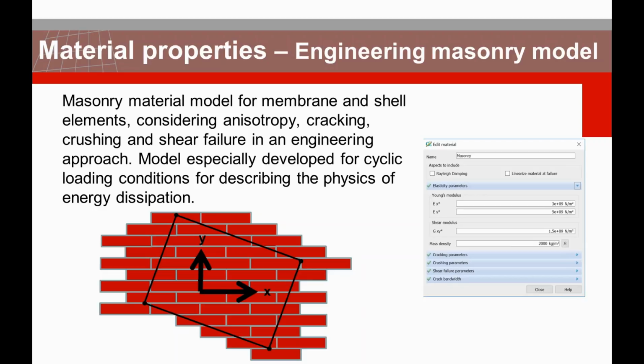So when there is a crack, the model is anisotropic, nonlinear till the failure. When it's failed, you can continue the analysis because the failed element is at utmost failure. There is no more resistance, but with linear elastic properties, and you can continue with the analysis.